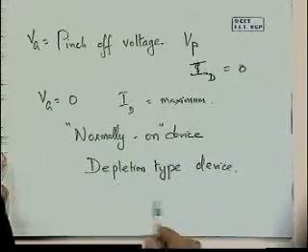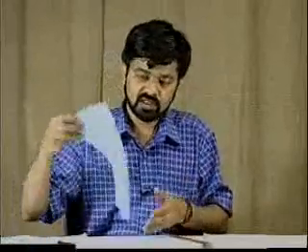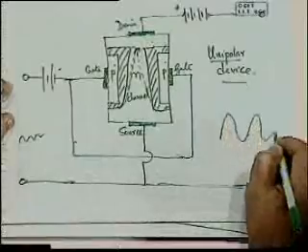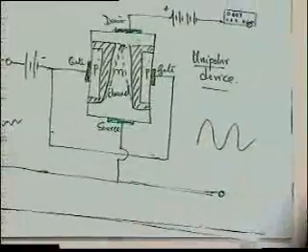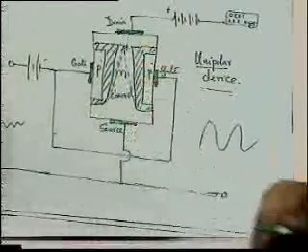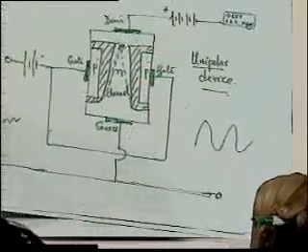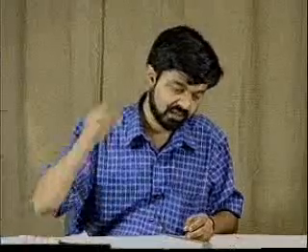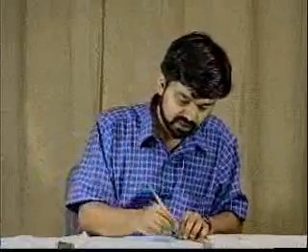And again, the idea is very similar to a BJT: if you modulate the gate voltage, instead of having a simple change, you can apply some modulation to it on this circuit here. You will get the modulated value on the other side. A very small change in gate voltage gives a very large change in the source to drain current that we can see. So we can get the same kind of amplification behavior even using a JFET.